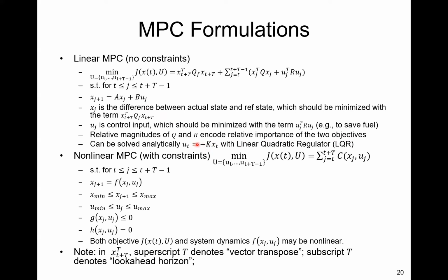You can solve it analytically with the linear MPC formulation, but with nonlinear MPC, the system state x_{t+1} is a nonlinear function of the state x and control input u, and the cost function may also be nonlinear, and you may also have constraints on state x and control u. For example, u may have an upper bound based on the physical limits of your actuator.